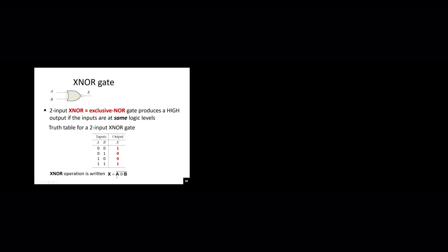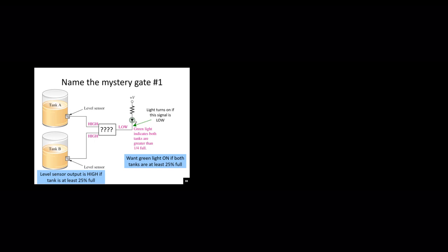And just like before, if you want to write down XNOR using maths or using symbolic logic, we write down the XOR first, remembering that the XOR symbol was this little plus with a circle around it, and we put the bar across the entire top to tell us that the NOT comes after the XOR gate. Okay, right, that's a lot of gates.